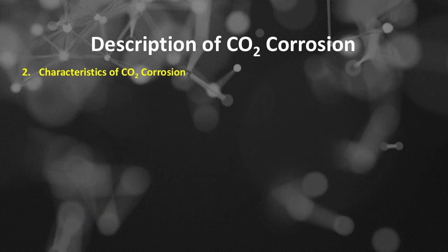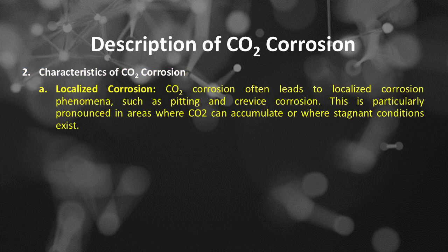Number 2 is characteristics of CO2 corrosion. Number A, of characteristics of CO2 corrosion is localized corrosion. CO2 corrosion often leads to localized corrosion phenomena, such as pitting and crevice corrosion. This is particularly pronounced in areas where CO2 can accumulate or where stagnant conditions exist.